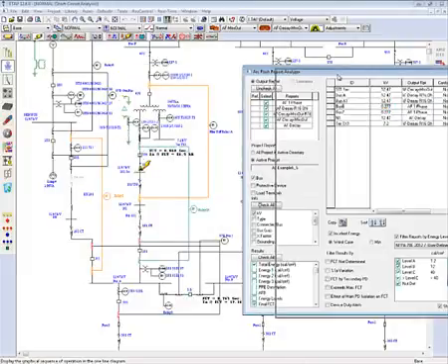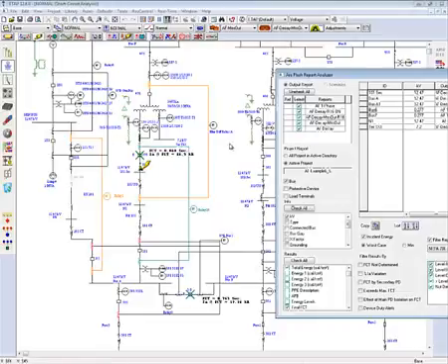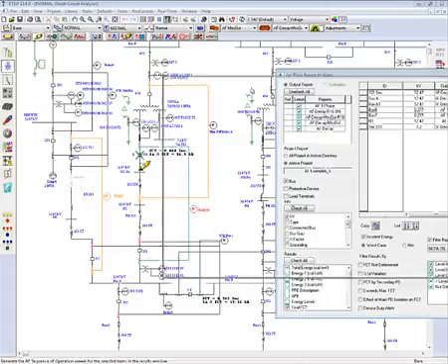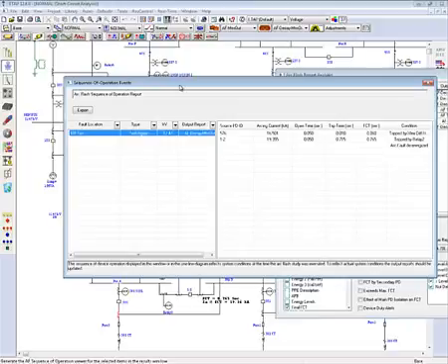Let's move this to the side. Now, as you can see here on the one-line diagram, I do have a fault clearing time determination, but my relay 16 differential is not operating 101. Furthermore, if I were to actually launch the viewer, I can see what actual relays are operating.